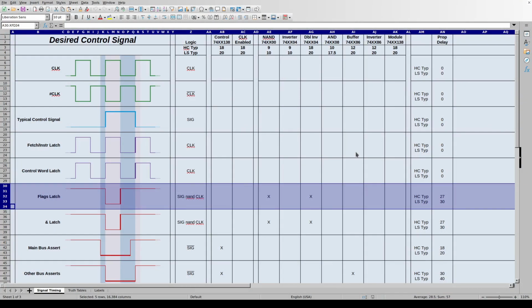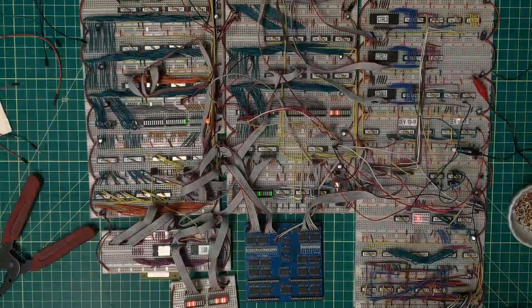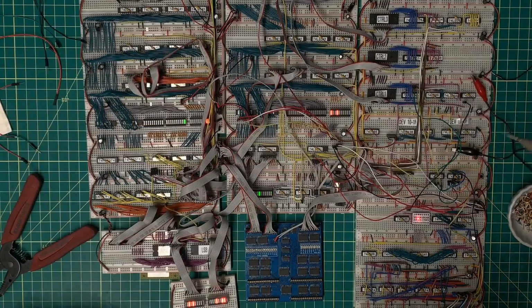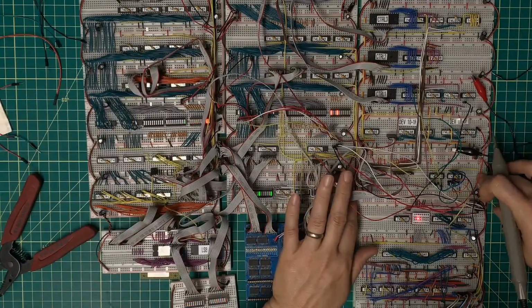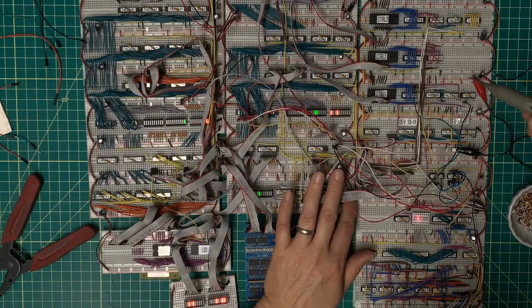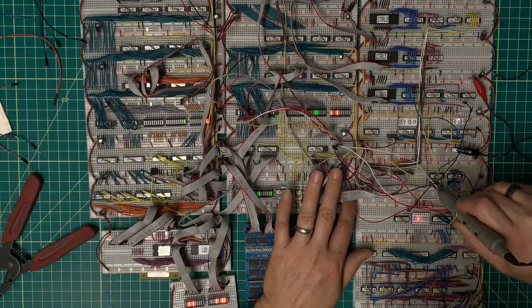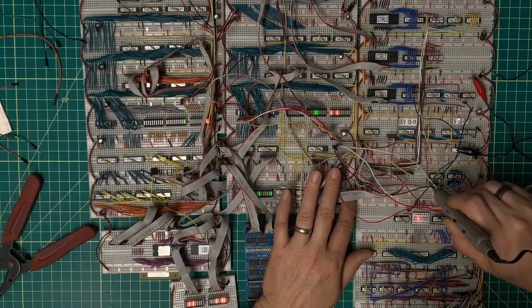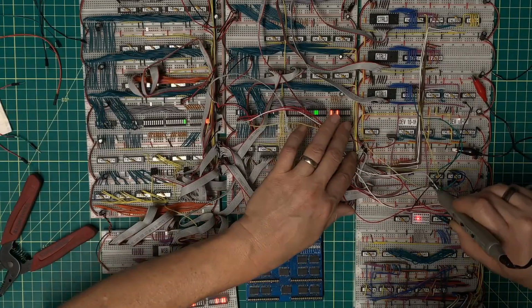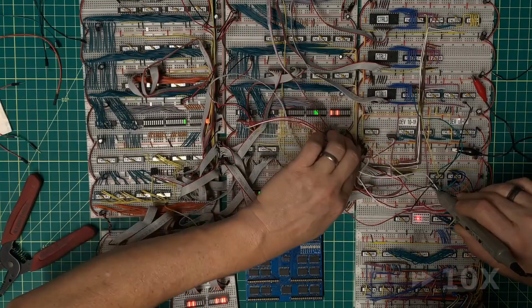Let me come back here to my application here. That looks reasonable to me, by the way. So I've got the probe hooked up again. I've reset. And the signal I'm looking for here is low. My clock right now is floating.